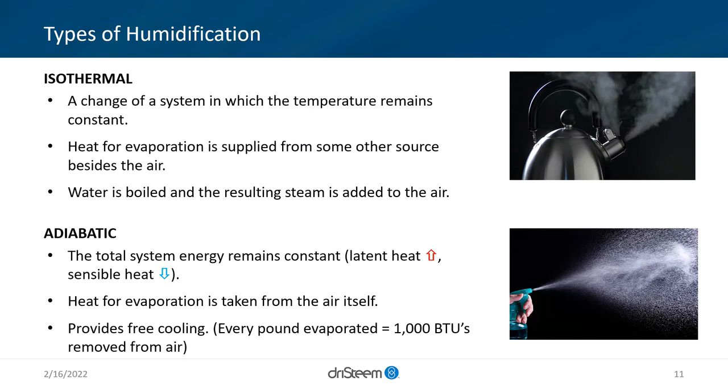We're not going to get super into the psychrometrics of this. Obviously, you have to have that differential of RH available to get that cooling. If you're already at set point, you're not getting any cooling from that piece of equipment because it won't be running.